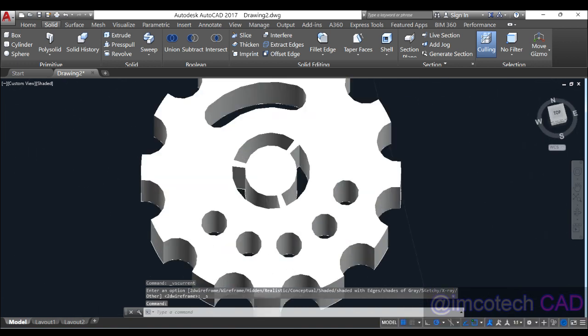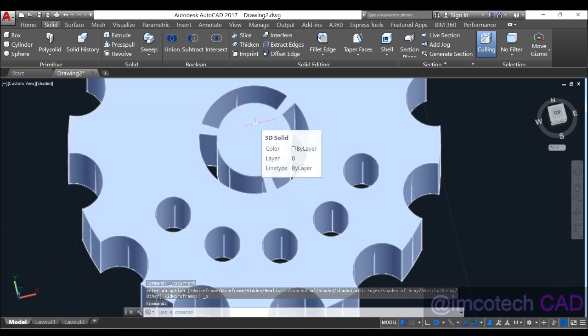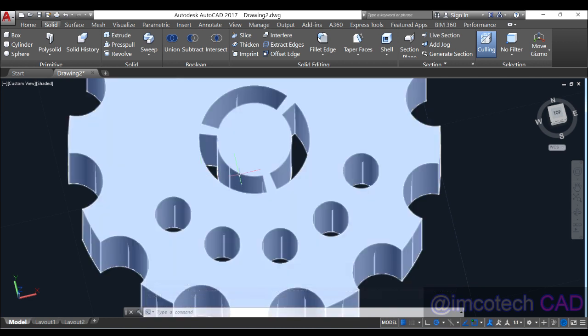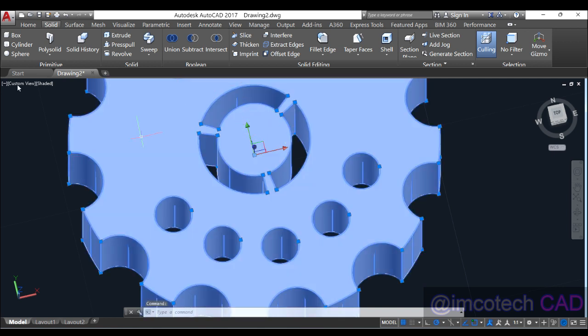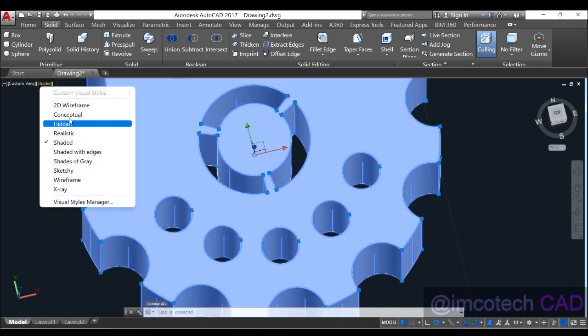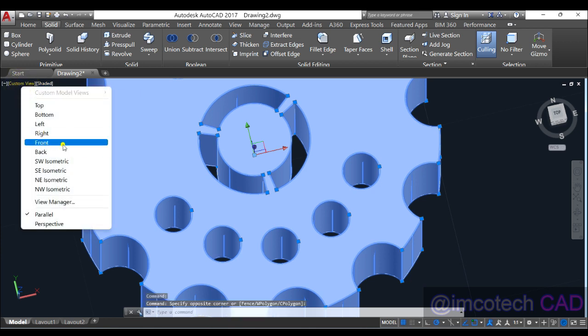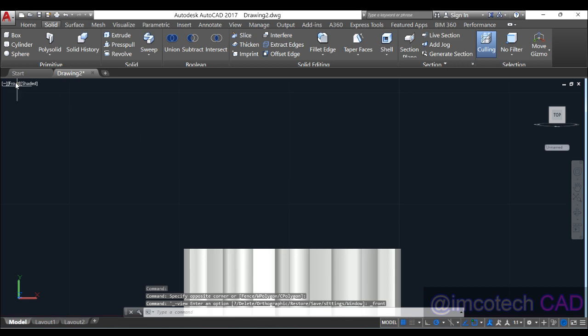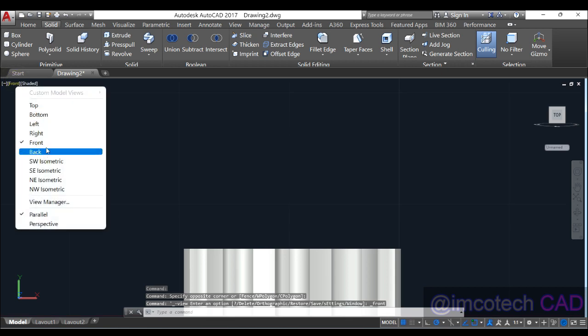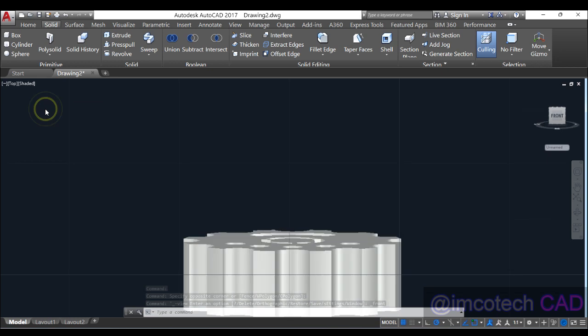So the next thing is I'll have to make a hole, although the hole is not part of this design because the original design was 2D, right? So let's make a hole right on this plane. I'll simply go to this place and custom view, and maybe select, okay, because we did not use the front plane, so let's select the top plane.